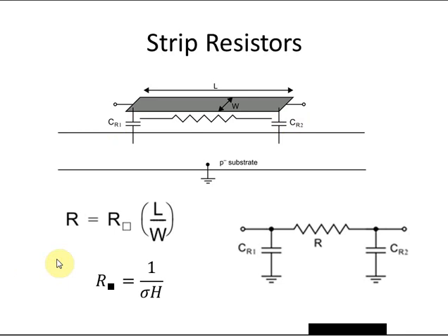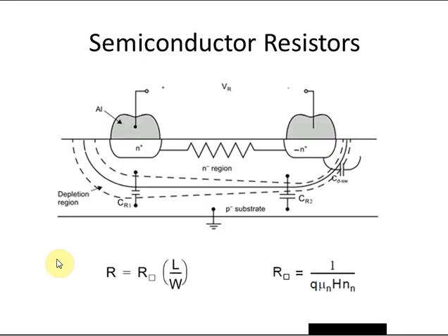Now, of course, let's not forget that there's another way to build resistors using another conductive strip, if you like, that's actually embedded right in the silicon, and that's simply to use an isolated well region as the resistor. After all, any sort of doped semiconductor material has a certain resistivity, just like the materials we were talking about before. It has a resistivity that depends on its cross-sectional area.